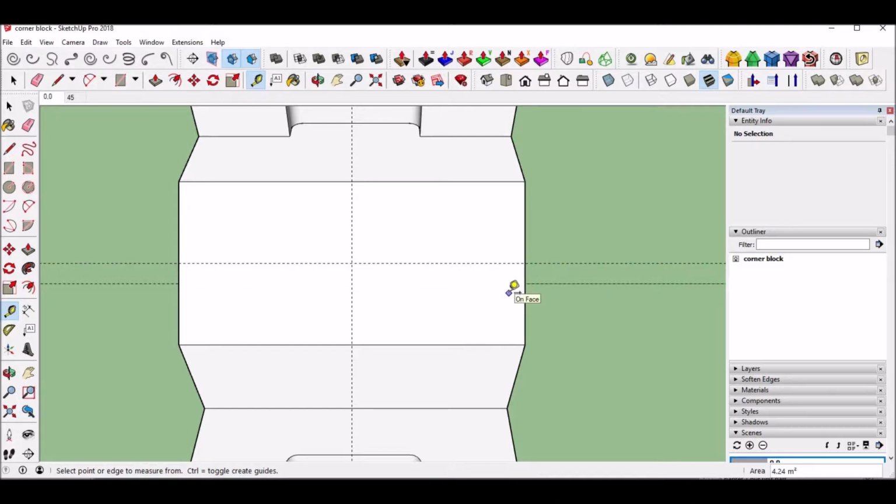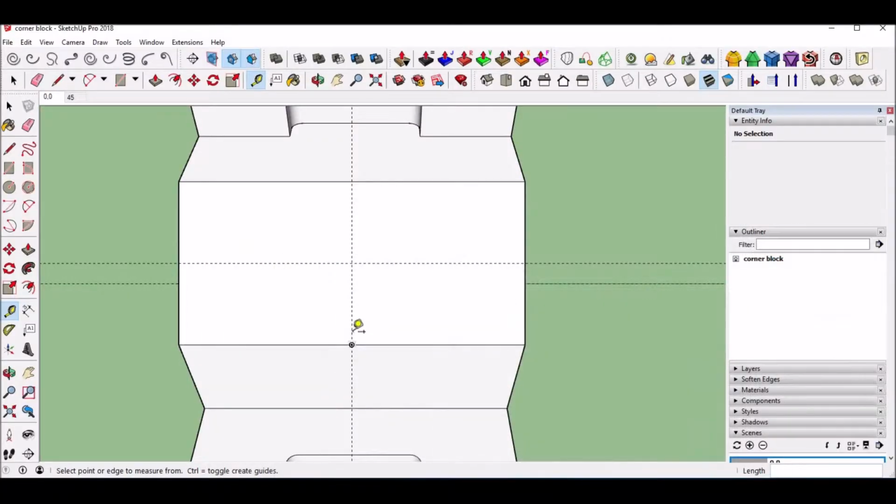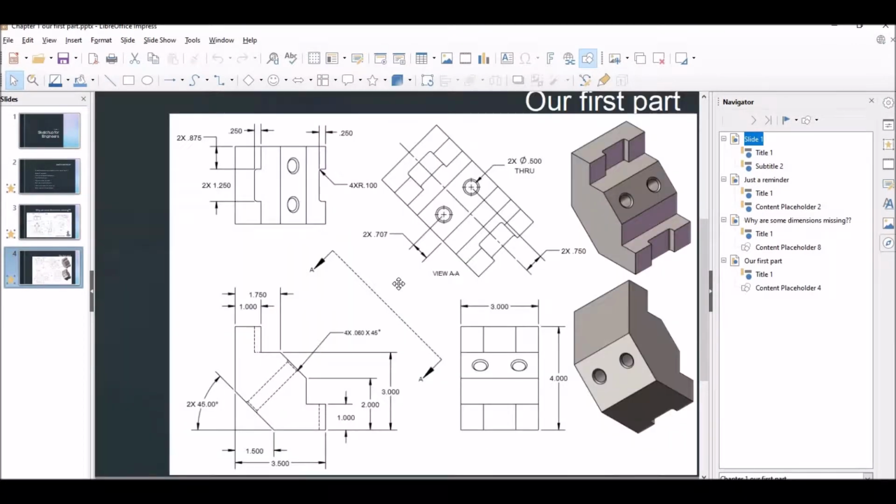We don't need that. And dang, I already forgot. It's a 1/4 inch, but which direction? Out that way. I mean, not a 1/4 inch, 3/4. So this way, 0.75. Click this one, 0.75. Now remember, when you move these lines, look where your inference line is. We're on the green. Don't want to hit up arrow and have something crazy, so make sure you're in the green.